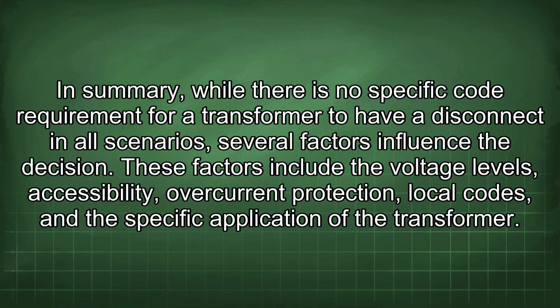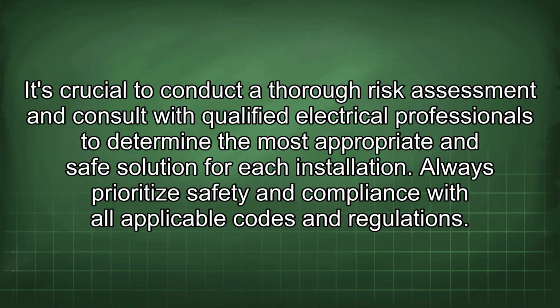In summary, while there is no specific code requirement for a transformer to have a disconnect in all scenarios, several factors influence the decision. These factors include the voltage levels, accessibility, overcurrent protection, local codes, and the specific application of the transformer. It's crucial to conduct a thorough risk assessment and consult with qualified electrical professionals to determine the most appropriate and safe solution for each installation.